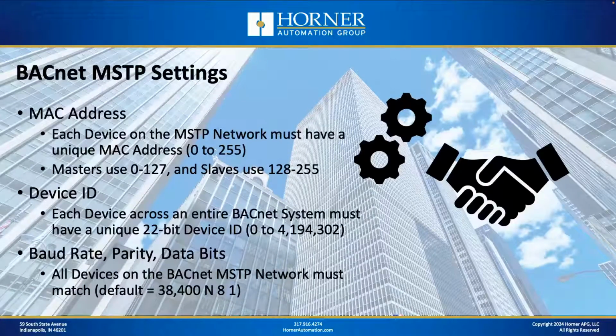I believe the default is 38,400, no parity, 8 data bits, and 1 stop bit. I think those are typically used as the default for BACnet, but of course, double check me on that.